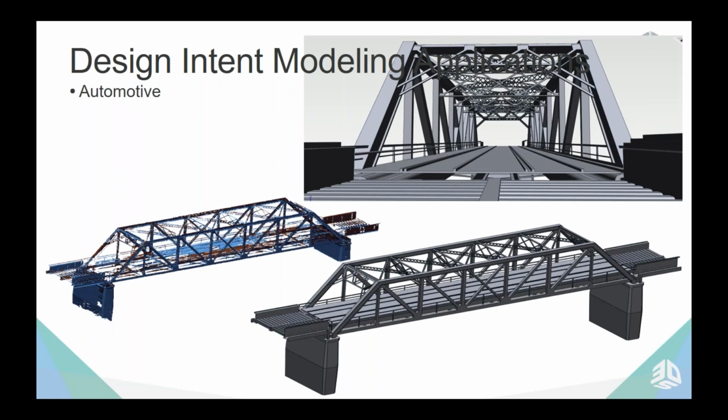And of course, taking this back to the conversation that Ian started earlier about accuracy versus resolution, these scanners that are long range scanners are accurate to within a couple of millimeters. So if we see some deviations up to that point, a couple of millimeters really isn't much in the grand scheme of things on something the size of a railroad bridge.